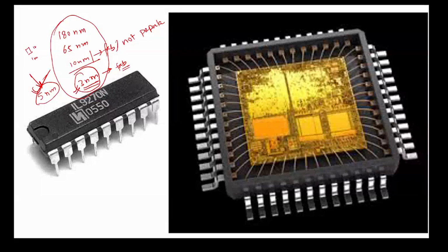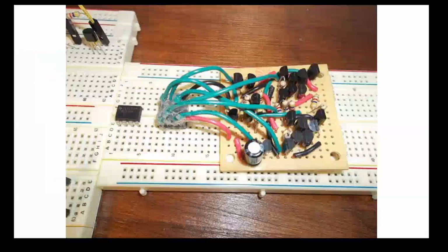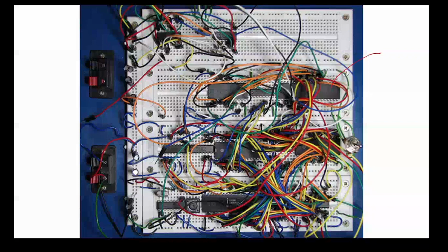And there is another advantage. For example, you have seen this board. These ICs are digital, but take a hypothetical case. Suppose this is a receiver antenna. After that, an LNA is there, then a mixer, a local oscillator, and other digital processing elements. So what will you do? Suppose you have different ICs: an LNA IC, a mixer IC, a local oscillator IC, and another digital IC.